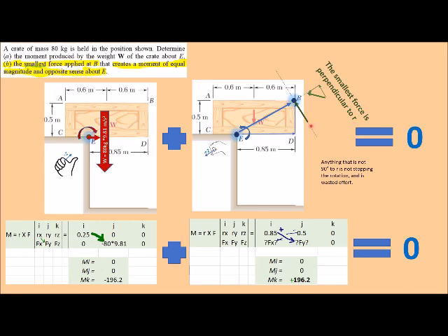And this is something we're not deriving numerically or analytically. We're just looking at the picture, looking at the free body diagram and thinking through what these angles should be. So the easier solution is to look at the picture of it and think through the angles and realize that the minimum force is going to happen when it's perpendicular to the position vector.